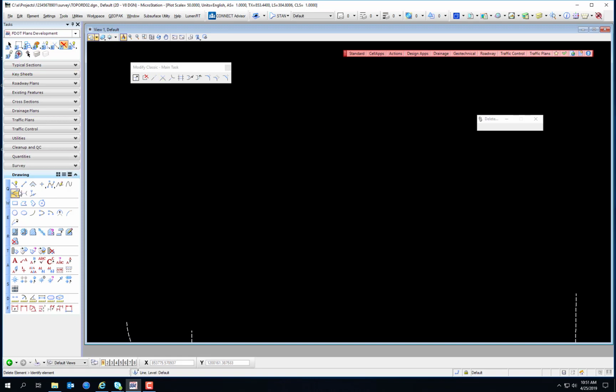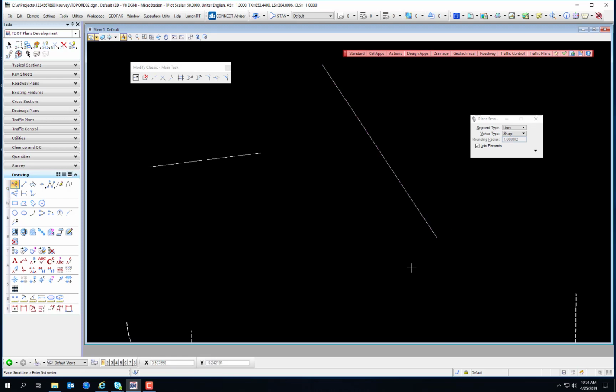Trim to element. Alright, two lines that would not intersect, or that would intersect. They are not parallel, but do not yet intersect. Trim to element. Select the element to modify. I want to trim that element. And then select the cutting element, which is not really a cutting element, it's the element to which it's going to be trimmed.